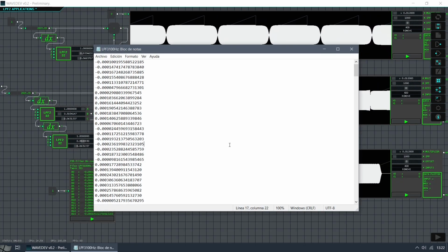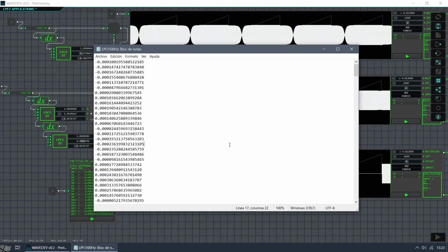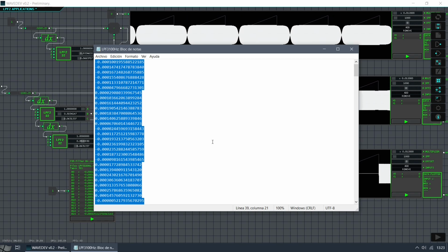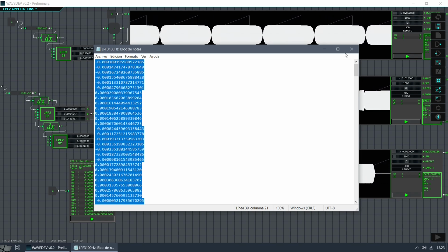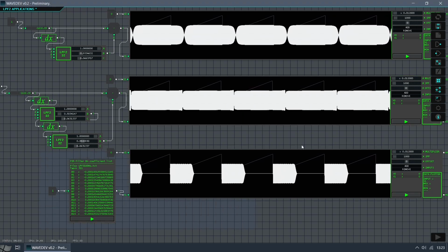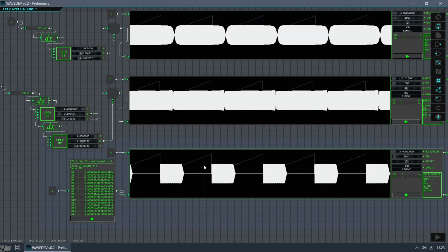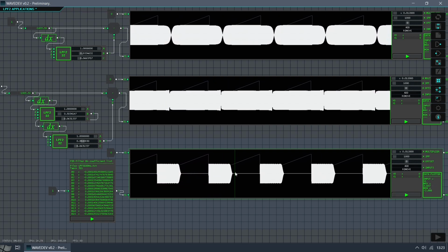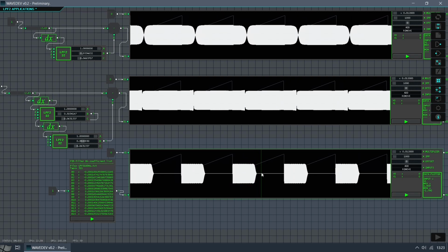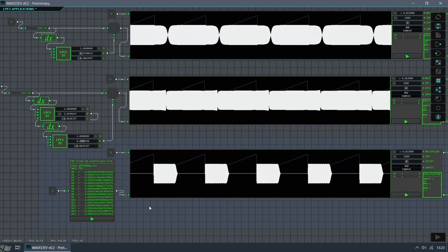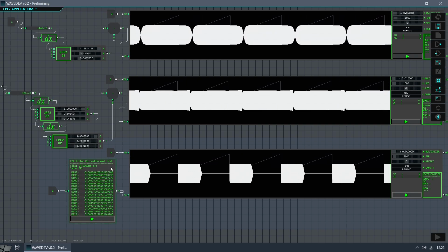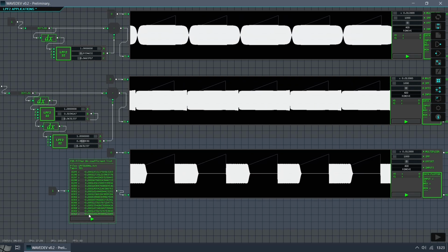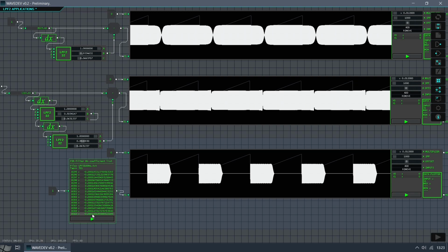Finally, as a reminder, you have the option to use your own custom FIR filters. Just place your coefficients in a plain text file and you are ready to go. In this example, this low-pass FIR filter has a response far closer to the ideal than its first-order version. But here we are talking about more than 300 coefficients versus 2. We will return to this filter in a while.